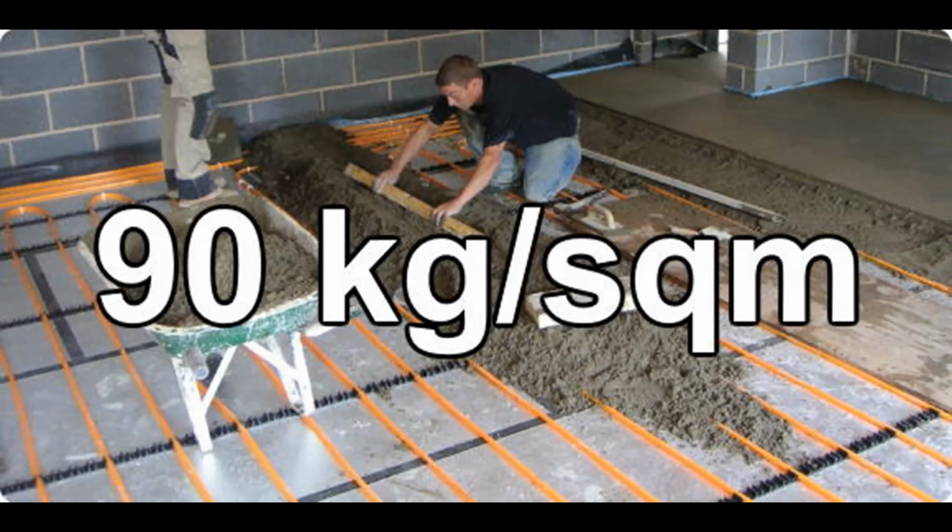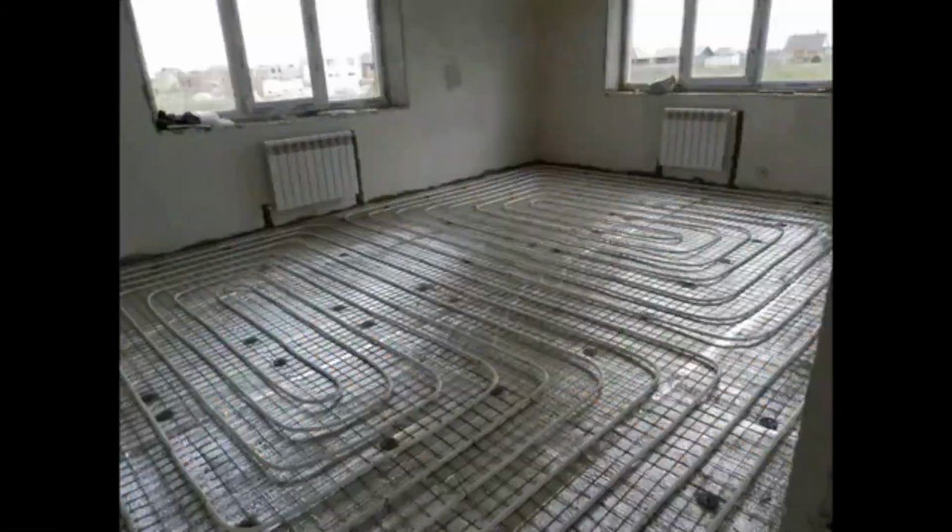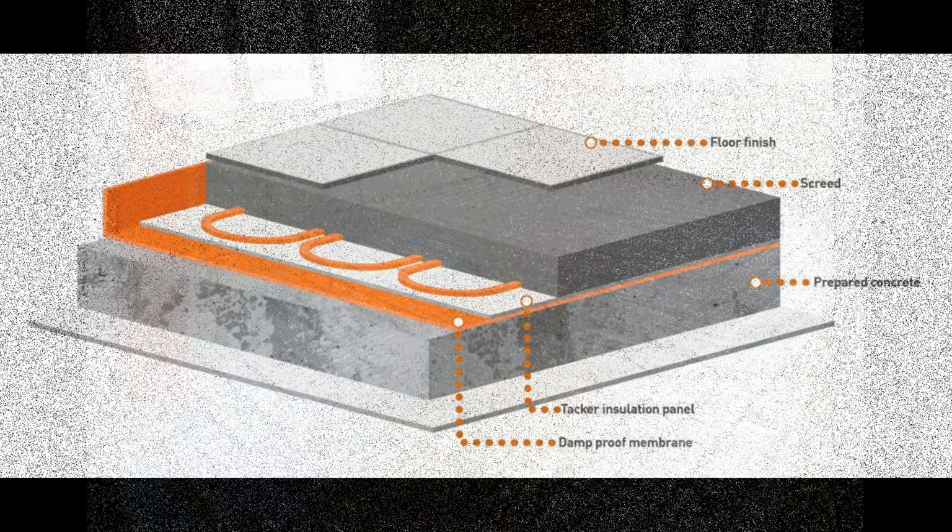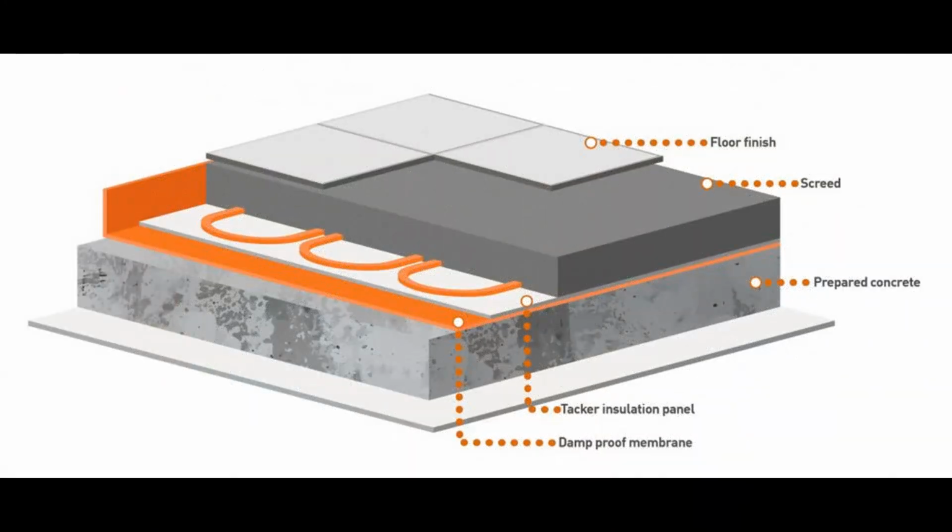Such systems are very difficult to use when installing in apartments, especially in old houses connected to the city heating system. There is a large thickness of the underfloor heating system with insulation when we use a screed solution. Since under the screed the floor needs insulation, that is the minimum thickness of the insulation and screed. This is a minimum of 120 mm.